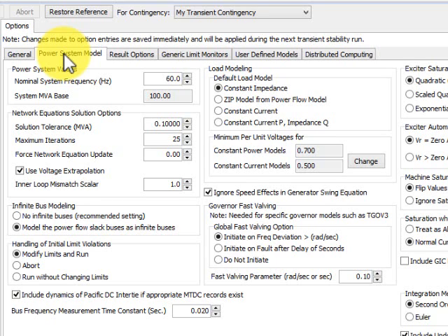Oh, this used to not be on this page. I don't remember this. The constant power loads at 0.7, voltage sensitive. So this must be in response to the failed network equations at Centralia. It was the older or the previous load model. There was a large constant power component for the station service load, and so then it would just stop. And so I think this was apparently the fix for that.